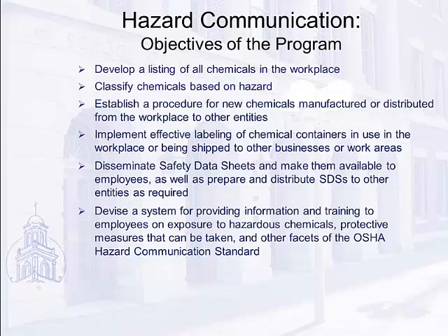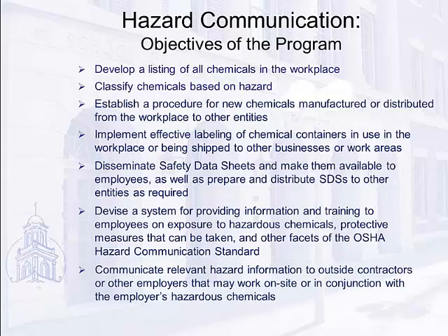Devise a system for providing information and training to employees on exposure to hazardous chemicals, protective measures that can be taken, and other facets of the OSHA Hazard Communication Standard. Communicate relevant hazard information to outside contractors or other employers that may work on-site or in conjunction with the employer's hazardous chemicals. Everyone working around hazardous chemicals and other toxic substances has a right to know of possible dangers and